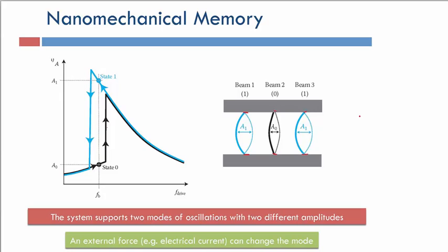the string. Well, these beams are a little more interesting than the traditional violin strings, in that they have this bistable mode, where if the driving force FB is at the proper frequency, the system can vibrate with either amplitude 1, a high amplitude, or amplitude 0, a low amplitude.